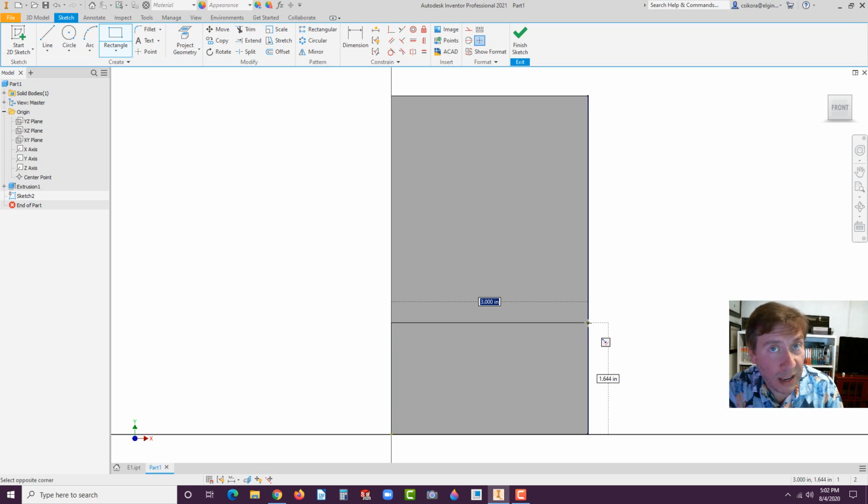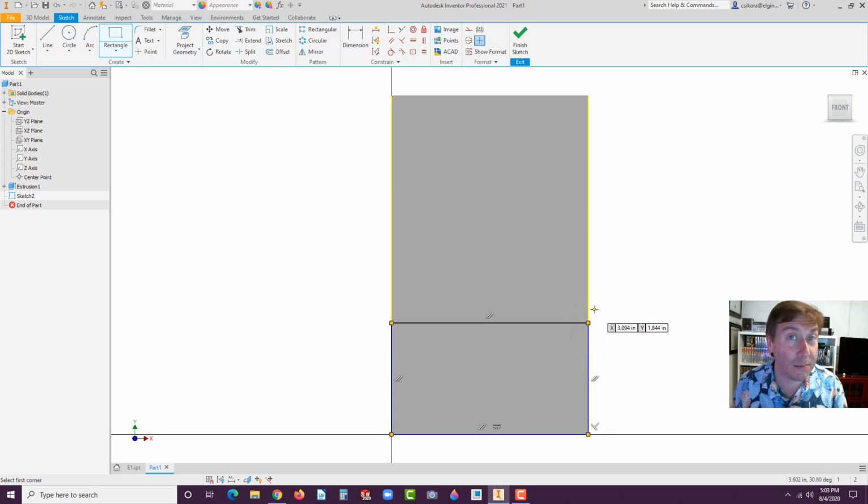Now there's 2 layers of dimensioning and constraints that you have here. You have the ability to use dimensions, and you have the ability to use relationships, which are constraints like coincidency, tangent, perpendicular, parallel, things like that. Now, if we were just to click on this edge, it's going to default to the coincident relationship to the right edge, so it's locked in. So it doesn't need that 3-inch length. But because I clicked there, it negated the dimension to the right for how high we wanted it. Now we could have gotten it to the midpoint, but that's not what we wanted.